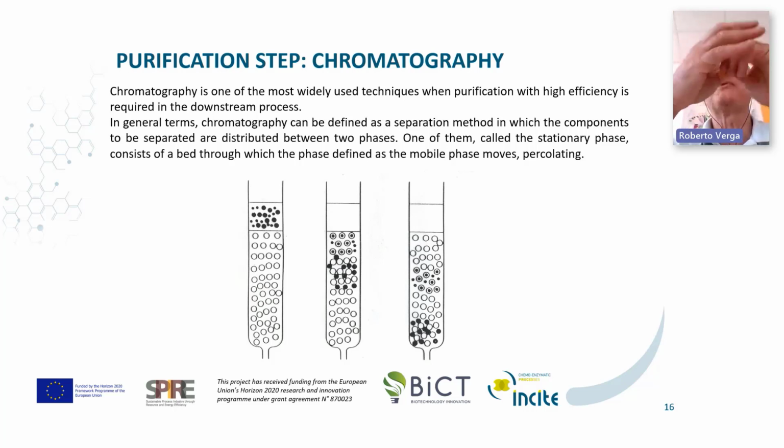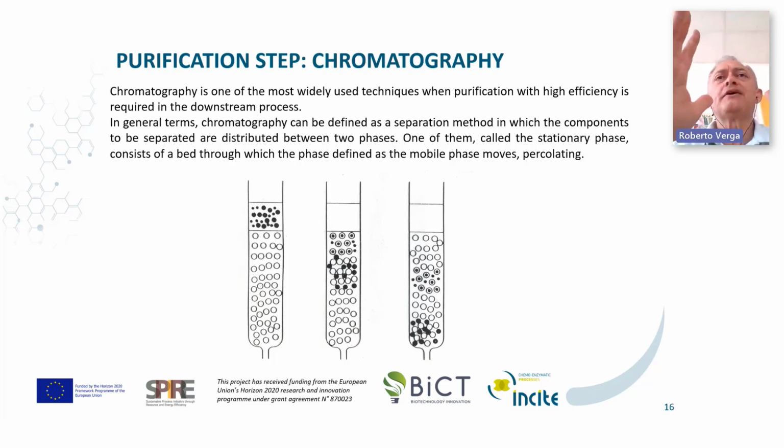This is the chromatography. What is the chromatography? It's a particular technique, very consolidated, but in general it is performed in a column, glass column or stainless steel column for the large scale, where I can recognize two phases, one liquid phase, the mobile phase, and one fixed phase, the stationary phase, composed generally by beads of resin.